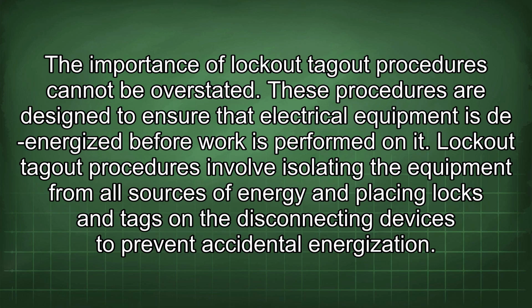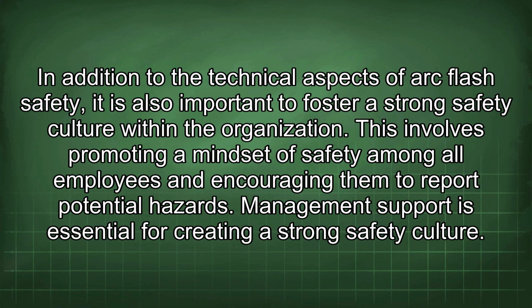The importance of lockout-tagout procedures cannot be overstated. These procedures are designed to ensure that electrical equipment is de-energized before work is performed on it. Lockout-tagout procedures involve isolating the equipment from all sources of energy and placing locks and tags on the disconnecting devices to prevent accidental energization.